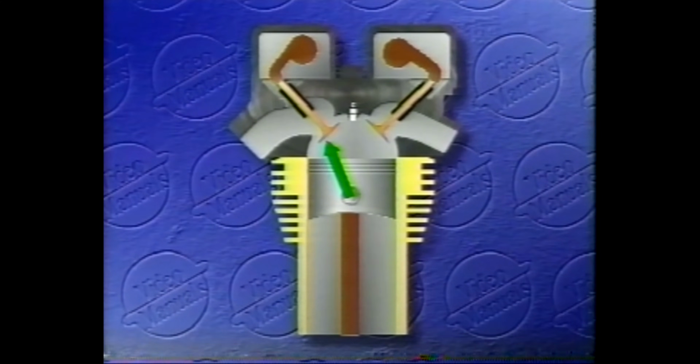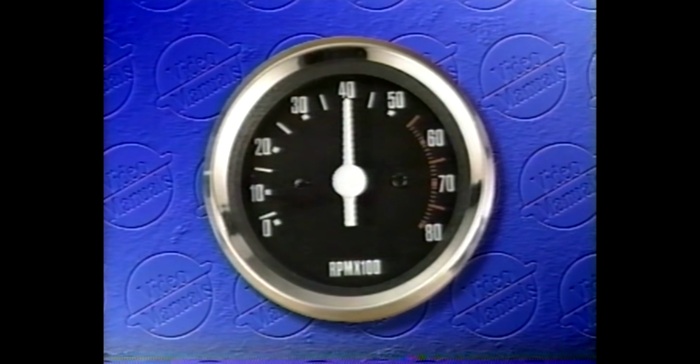If we advance our cam, we must recheck the intake piston to valve clearance. The camshaft will have moved the maximum valve lift point closer to top dead center, bringing the piston and the intake valve closer together. Similarly, if we retard our cam, we must recheck the exhaust piston to valve clearance. If we advance our cam by 4 degrees, we will lower our engine's power band by 200 to 300 RPM. Conversely, if we retard our cam by 4 degrees, we will raise the power band by 200 to 300 RPM.